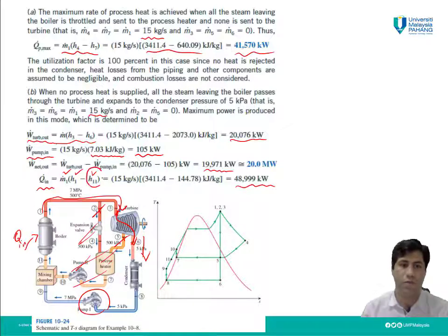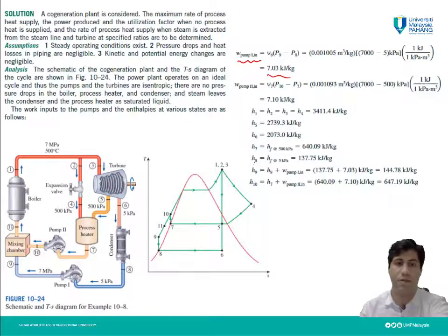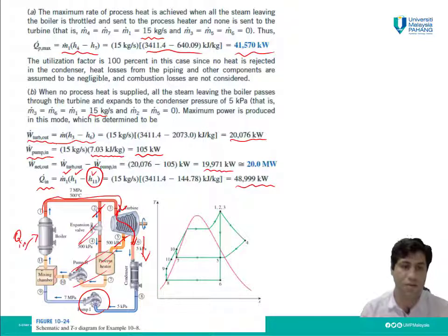However, if you notice, we didn't calculate h11 in the previous slide. Why? Because h11 is after the mixing chamber, and according to the structure of the mixing chamber, there isn't any change in the temperature, pressure or state of the working fluid there. The purpose of the mixing chamber is simply to mix the two working fluids.